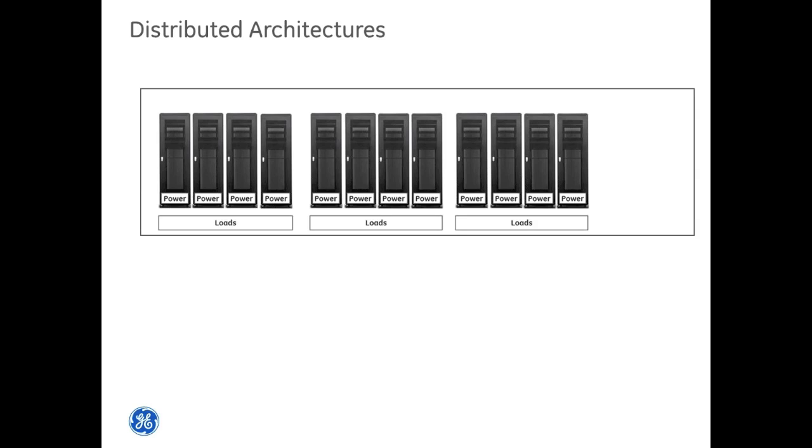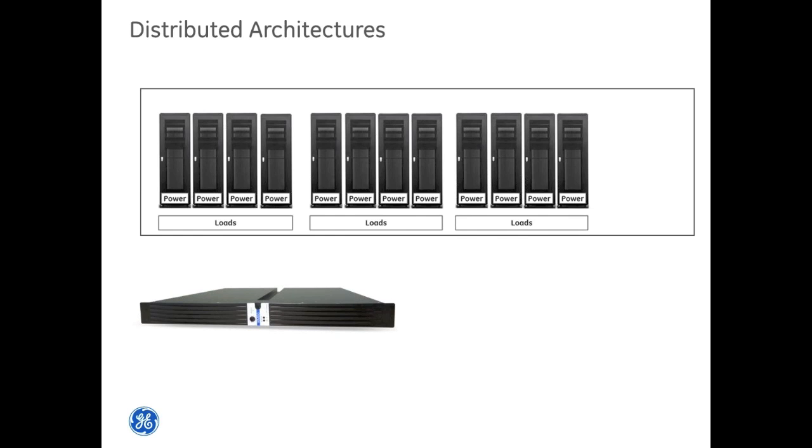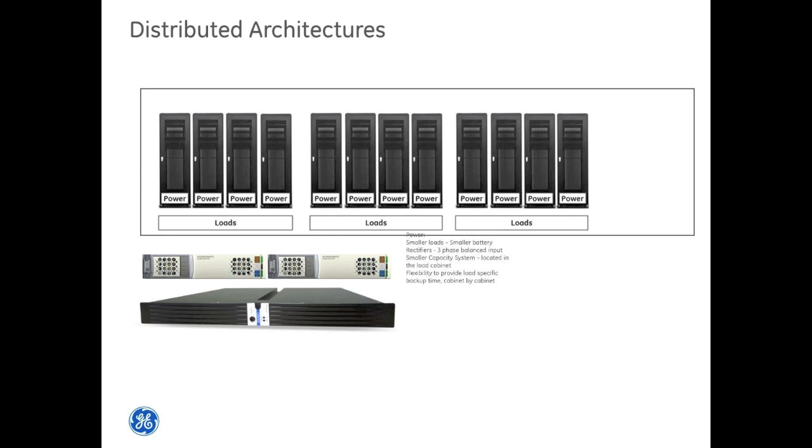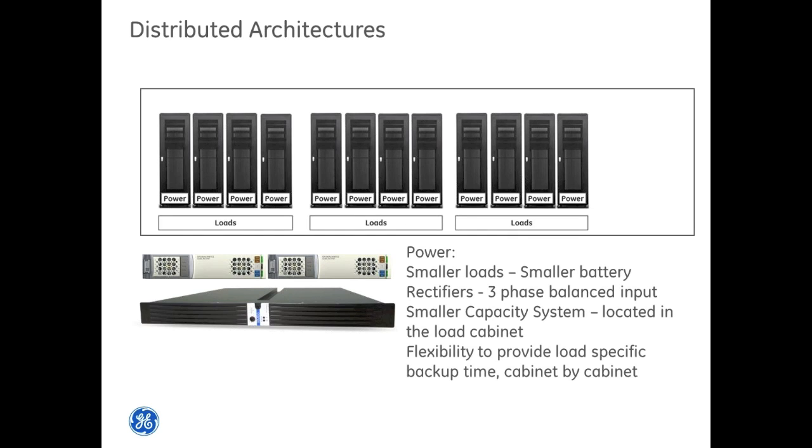I have a dedicated power area within each of my load cabinets. And you can see that, with the advent of some of these small batteries, small rectifiers, it gives you those same abilities with the smaller loads, smaller rectifiers, smaller capacity system. Now I can provide flexibility of the backup time at the cabinet level rather than the row level. So even more flexibility in terms of the backup time provided.